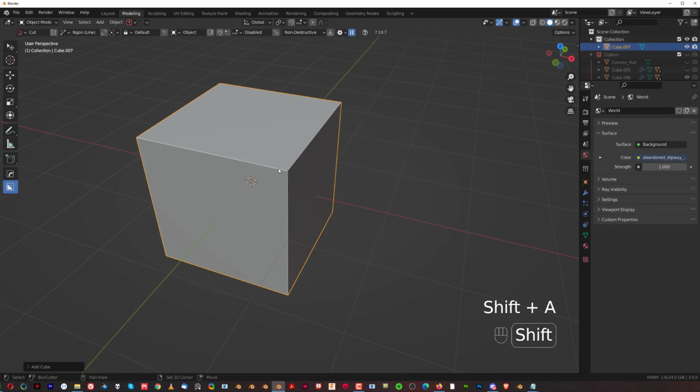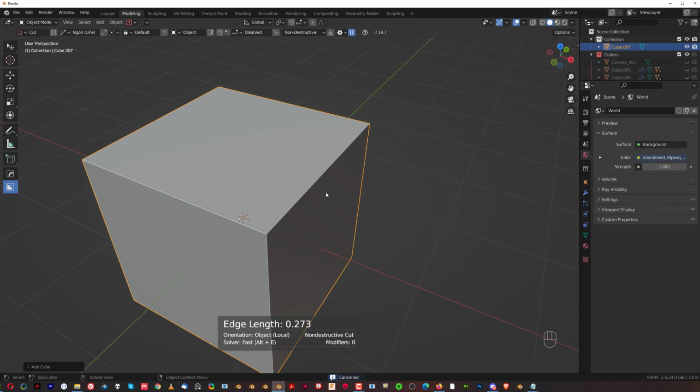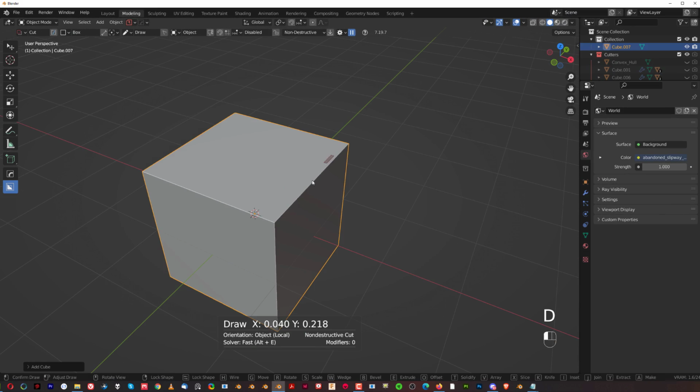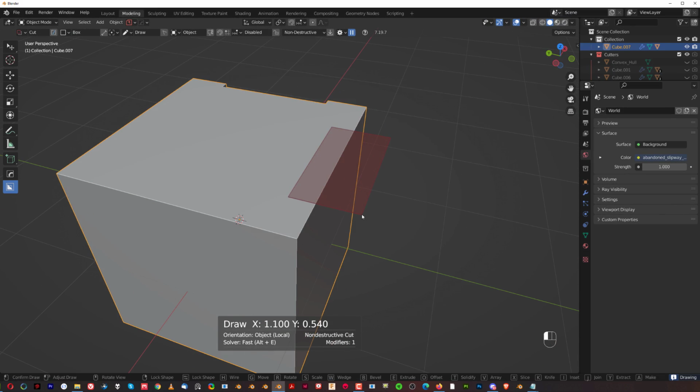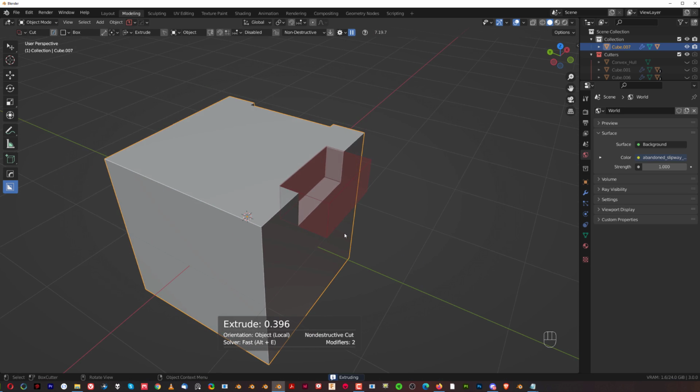Let's go and talk about some cuts, right? A normal cut with box cutter runs like this, okay? But what if you wanted to create a wedge? Well, a wedge is created by running a box cut and pressing W, okay? And then you can press W again, and you can cut it. But you can see that with this wedge cut, you don't really know which angle to pick.